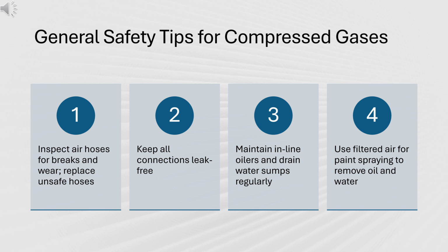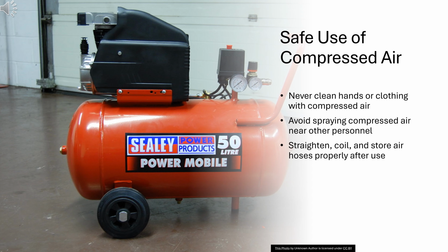To ensure safety, inspect air hoses frequently for damage, maintain leak-free connections, and regularly service inline oilers and water sumps. For paint spraying, always pre-filter the air to remove contaminants like oil and water. Compressed air must be used responsibly.